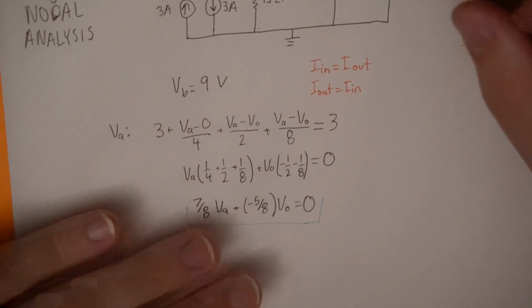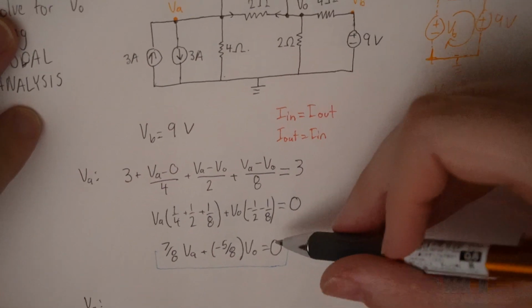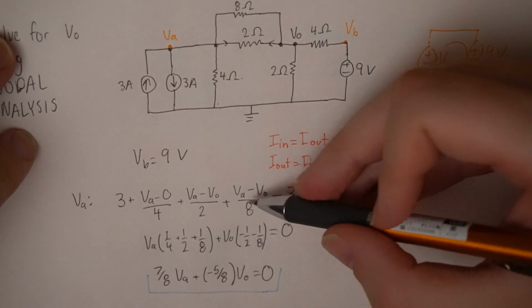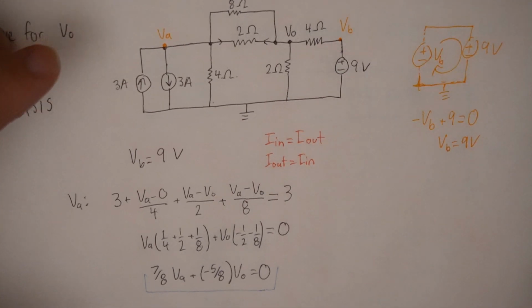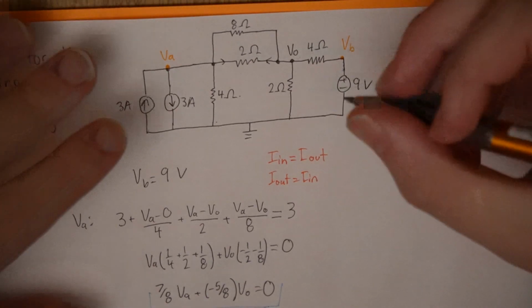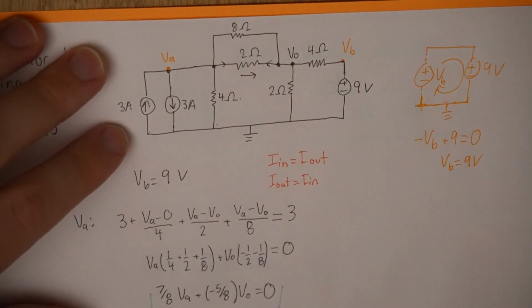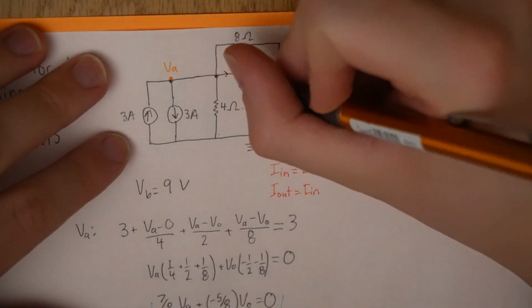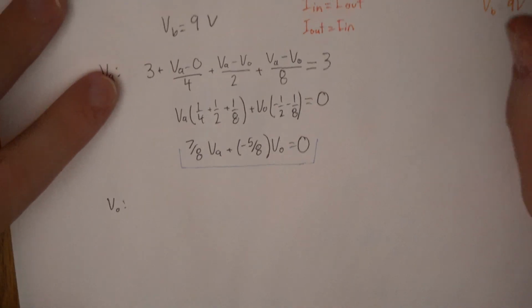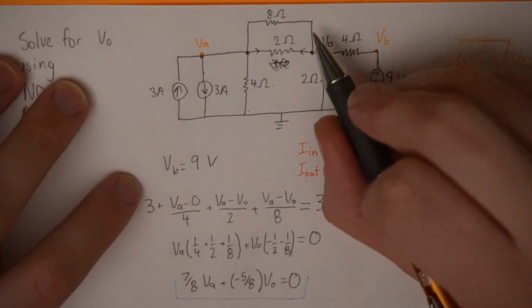However, when I write my equation, I'll swap the direction, but I'll also swap the order of the nodes in the circuit. So it's a double negative, cancels out. With this method, you don't have to draw arrows on each circuit. I can just use a simple method I'll show here. To show you how simple this way is, let's look at my node, VO.